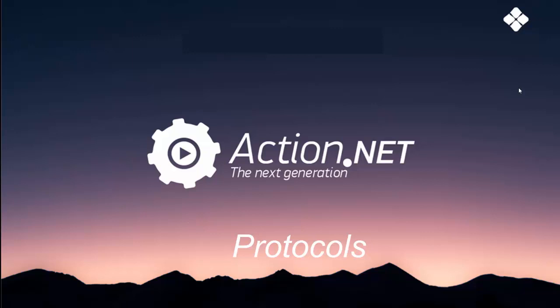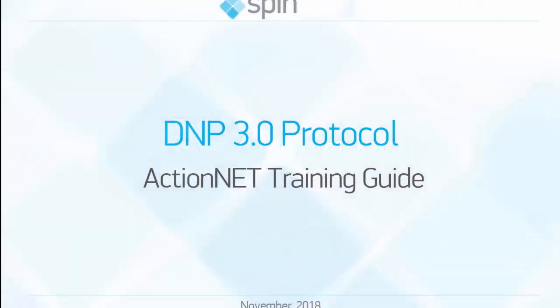In today's video, you will learn about DNP 3.0 protocol settings. This driver is used for communication with intelligent electronic devices, IEDs, that use the DNP 3.0, Level 3, protocol. Communication can be done through multi-point serial channel, or using Ethernet local area network and TCP/IP protocol, in which case, each IED has an IP address.